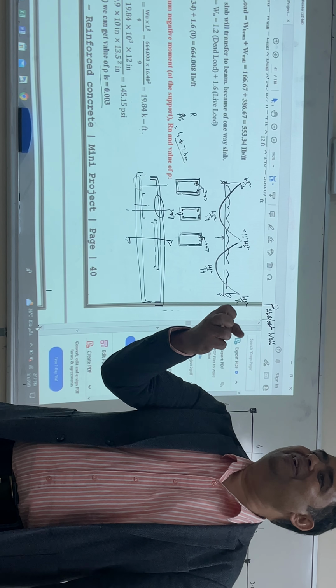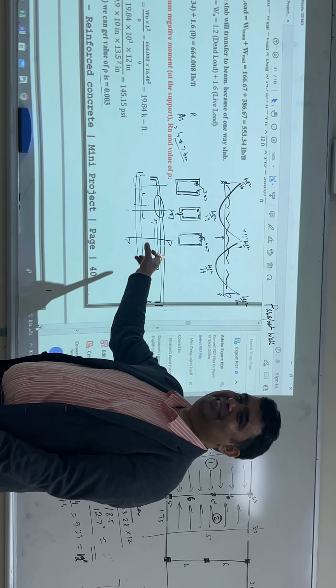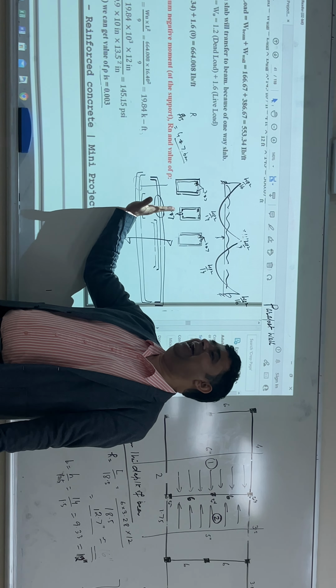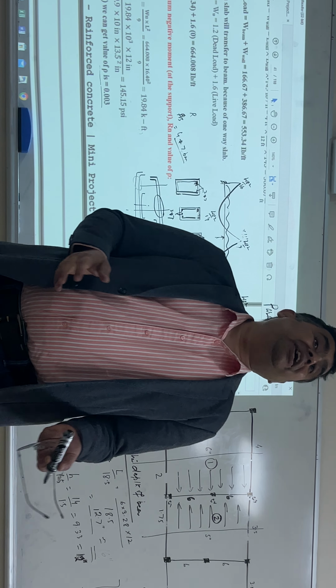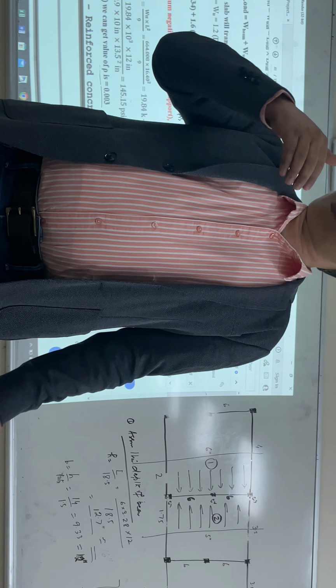So this means this. You understand the concept or not? Yes. So that is why we are always designing a doubly reinforced beam. Why are we wasting our money to only provide the reinforcement in the compression zone to support the stirrups? Why not take the strength of that, reduce the dimension, and then design it? So this way you have to design it, and the placing of the reinforcement you have to see.